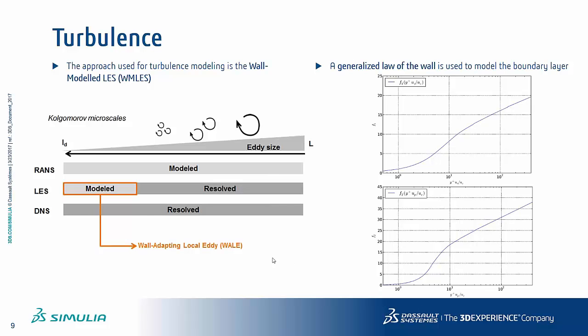In the meantime, there are 3 important things that make LES very well suited for Lattice-Boltzmann. First, we use an isotropic mesh, which is a lattice, which is perfect for the isotropy of the turbulence. Also, Lattice-Boltzmann is unsteady, so it's perfectly suited for LES. And finally, it's much faster in computation, as I will explain later.